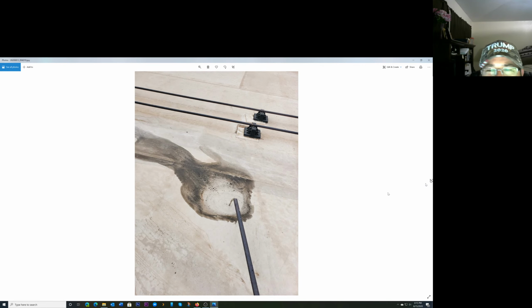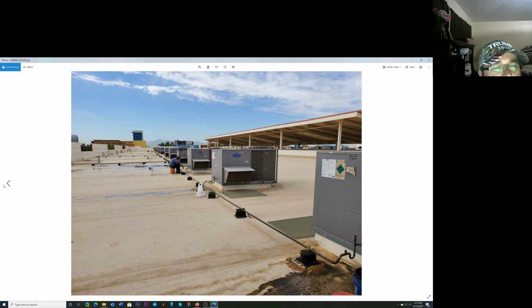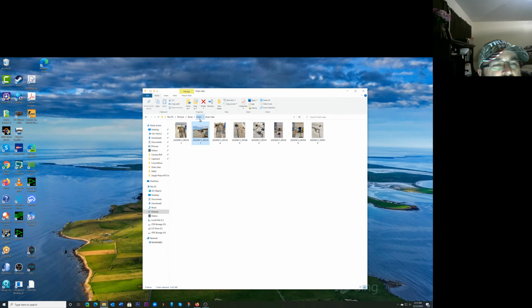So what the deal was is the other technician couldn't get it to blow because they're all interconnected. So if he tried to blow here, it would come out over here in this vent or whatever. And the restriction was down here in the 90, I believe. So we cut it over here in the main before it goes down and blew it and then put a bunch of unions in there. So I thought I had photos of the unions, but they didn't make it in there.